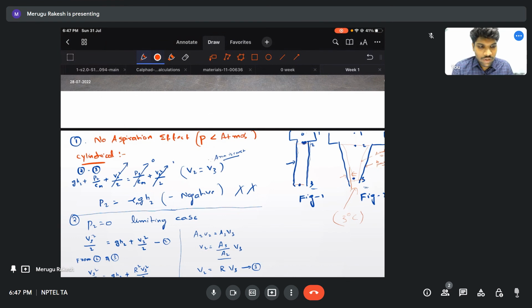And on the shrinkage dependency, there was a question about what the general values are. In general, shrinkage mainly depends on the cooling rate, how you are cooling it, faster or slower cooling rate, and on how the riser position is provided. The location of the riser should be well chosen in order to avoid shrinkage defects. But by any chance we should not allow turbulent flow while pouring the liquid metal into the casting. It should be laminar in actual practice.